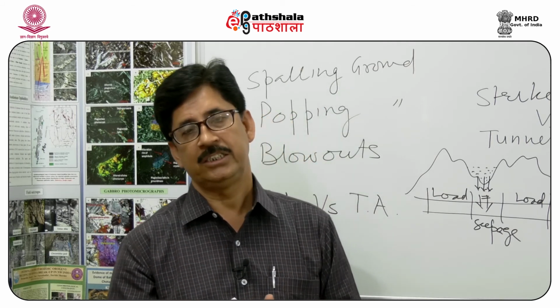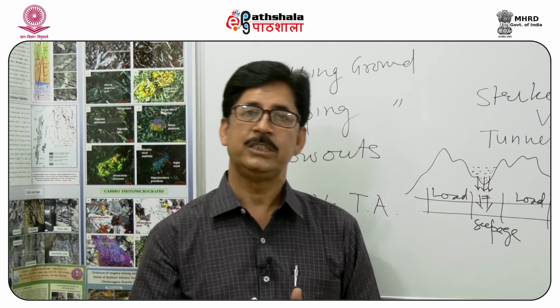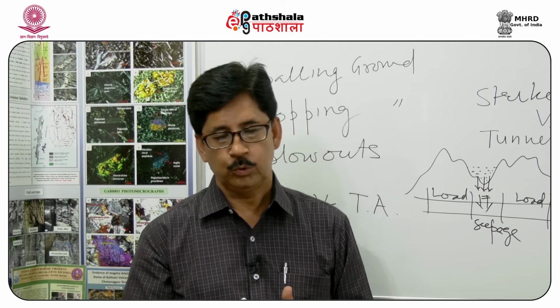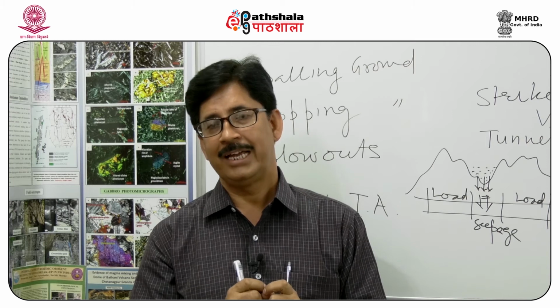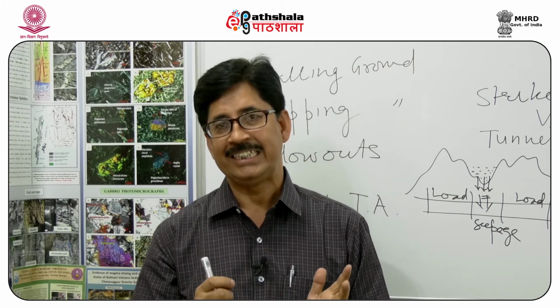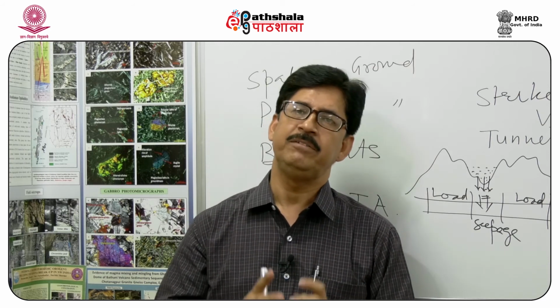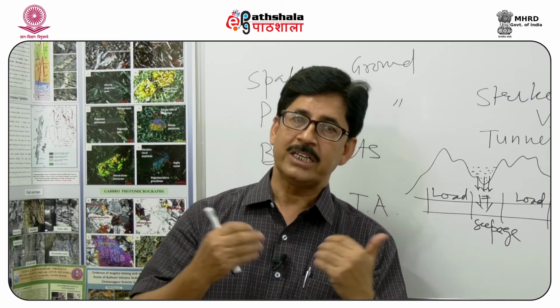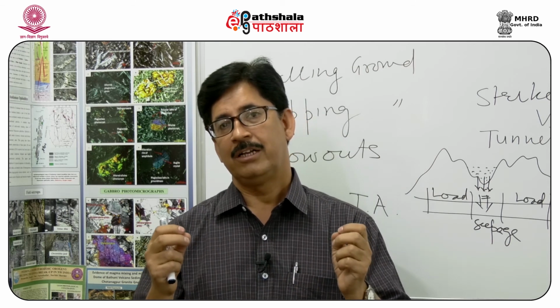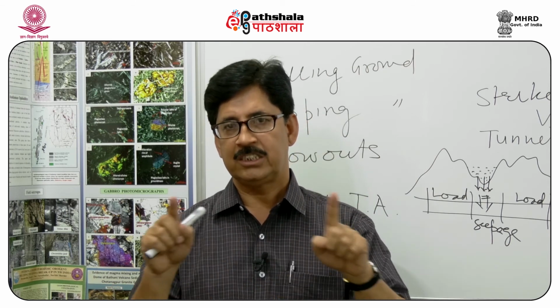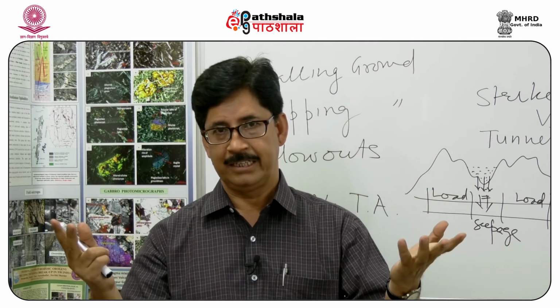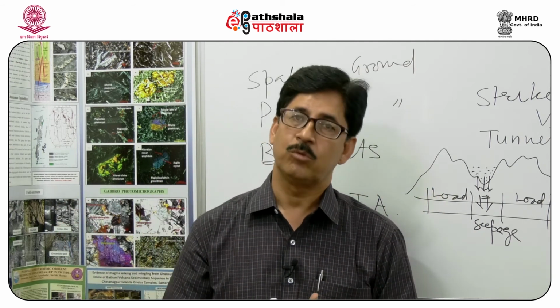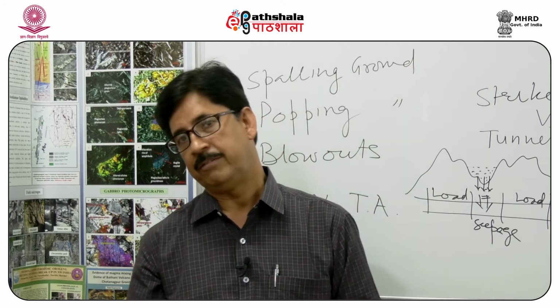Nowadays, apart from steel arches, the support system is mainly based on rock bolts which are 2 to 5 meters long. They can be installed through boreholes into the rock mass, and they can take load up to 60 ton. Sometimes if we have very weak rock mass, before excavation we first install rock bolts in spiling fashion just outside the required diameter of the tunnel, and then we go for excavation and we leave those rock bolts therein.